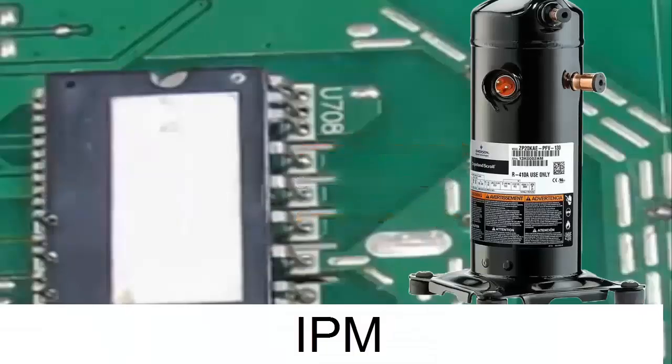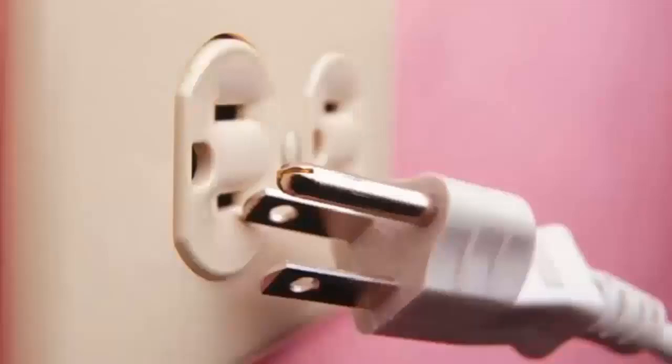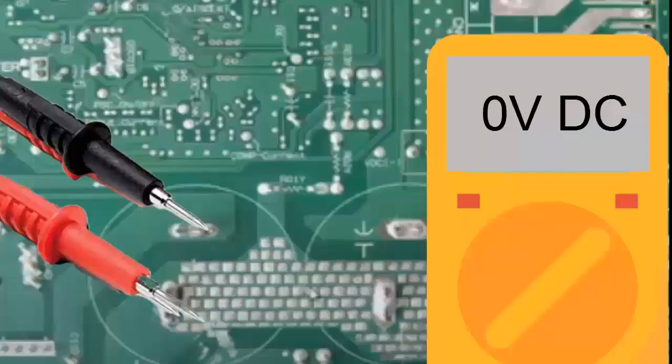1. Disconnect the equipment from the power supply. Remember that capacitors can store current. Use a multimeter on the DC voltage scale to measure across the capacitors and ensure they are discharged.